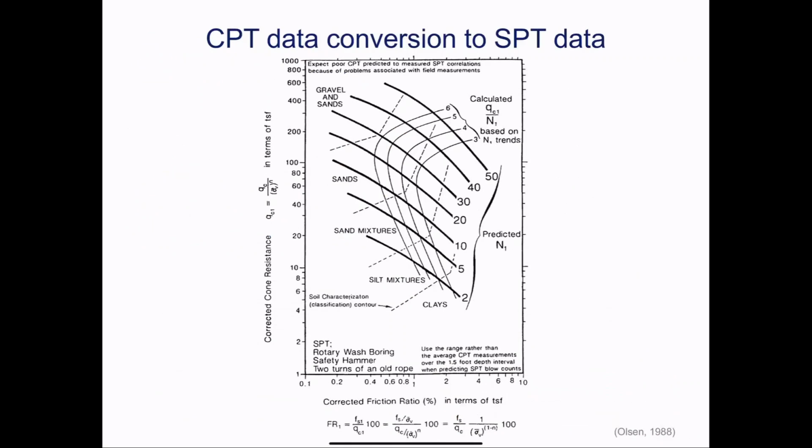There are also ways to convert CPT to SPT. Of course, this is very empirical, right? Because both approaches are highly empirical, but you can actually convert it. You'll even see sometimes when you get CPT data, you'll get depth, and one of the readouts is the equivalent N value from the CPT. So there are correlations as well.